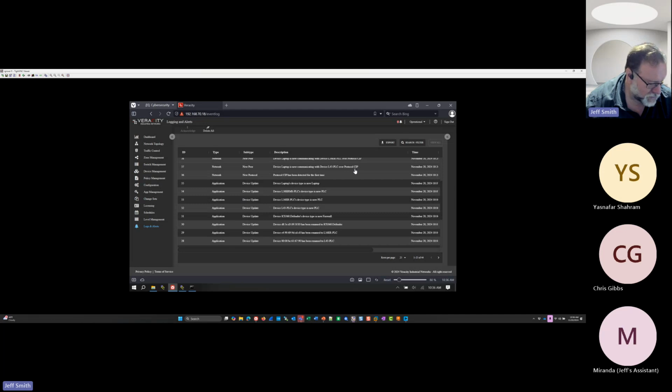There's a great northbound API on the controller, so higher level SIEMs can pull all the data they want from the SDN network. We have a number of customers in the past that have used tools like Nozomi or Clarity, and all they did was use those tools on the traditional network to pull all of this protocol information and all this type of data and send it to a higher level system. With the SDN network, you don't need to do that because the controller already knows all of that, and it knows it in nearly real time. Right? Clarity, Nozomi, Dragos, those are all applications that ride on top of a network. So they add traffic to the network, noise to the network. We know what's on the network in nearly real time, what it's communicating with, and that doesn't add any overhead to the network because it's a part of the network fabric. So it gives you a real picture of your network in nearly real time, which makes it nice.